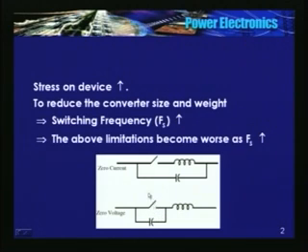Now I will open the switch. Since I have connected a capacitor, voltage across it cannot increase instantaneously. It will slowly rise, slowly increase. In other words, voltage across the device starts from 0 and slowly it will increase. Hence the name zero voltage switched converter. So these are the basic topologies, one of the topologies.